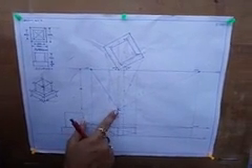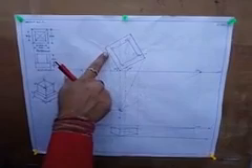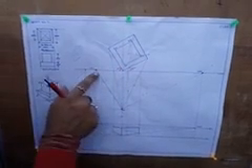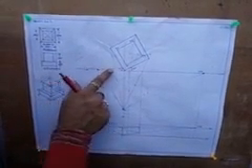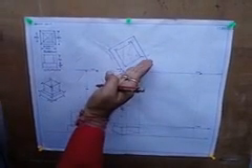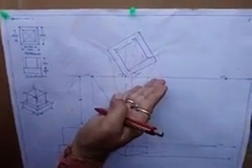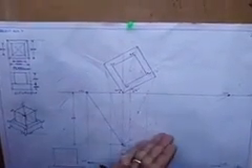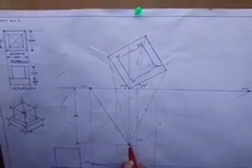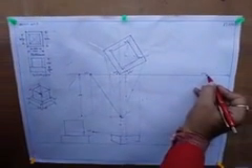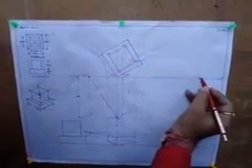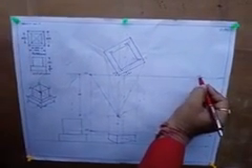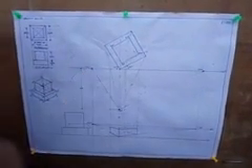After marking the station point, draw the parallel line from the station point to the side which is at the left side, which intersects somewhere on the picture plane. Then draw the parallel line to the side which is inclined to the left side of the picture plane, and this will intersect somewhere on the picture plane at the right side. So we get the intersection points as the vanishing points: VPR here is the vanishing point at right, and the vanishing point at left.